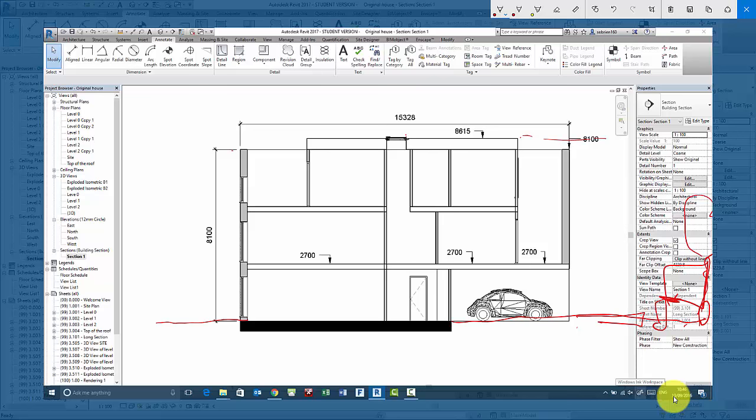If you say to the local authority, well, it's only ever going to be 8615 high, and then you go to the detail design, it turns out your roof light has to be this much higher, that might cause a problem. Depending on the personality of the person in there, that might actually cause you a lot of trouble. Something as simple as that.